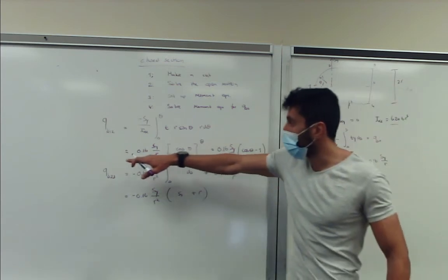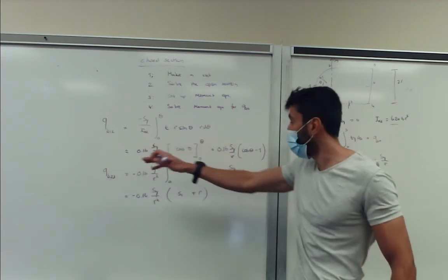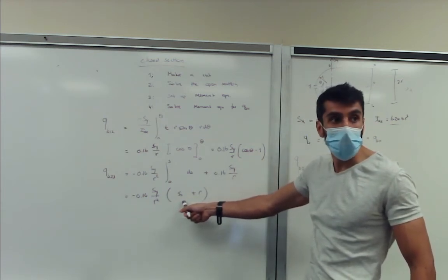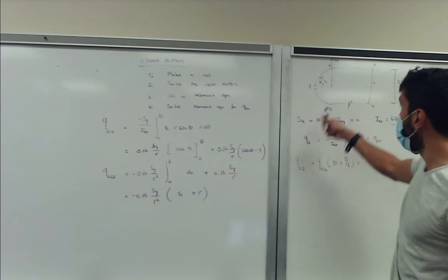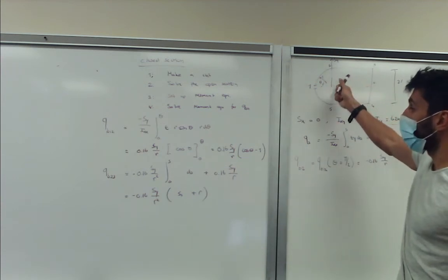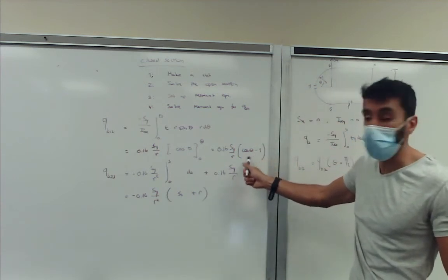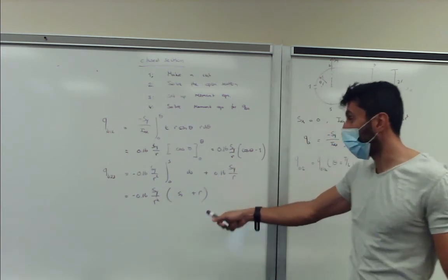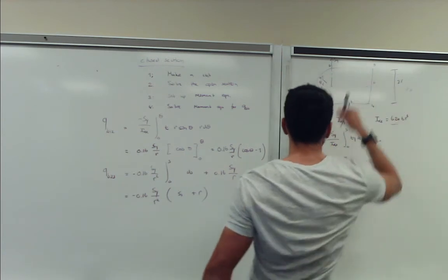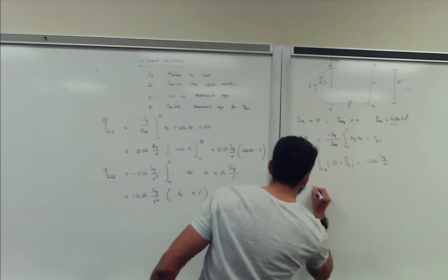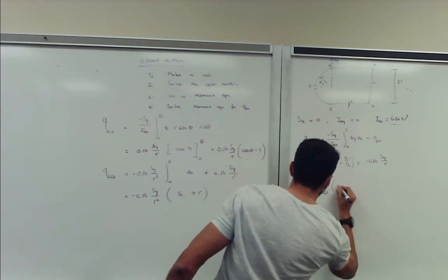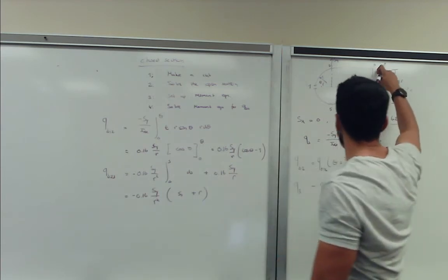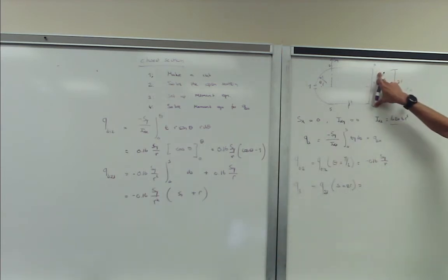So we determine the shear flow segment equation, which is basically still a function of, in this case, theta, and in this case, s1. And then, before we can continue to segment 2, we have to evaluate this at point 2 in order to find this start point here. And now we evaluate QB23 at point 3, so it's equal to QB23 at s equal to 2R, in order to find the start point for segment 3, 4.